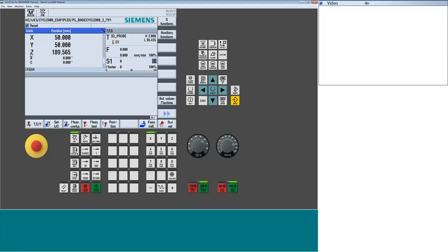So anytime you see a C axis defined, a rotary, because A, B, and C always refer to rotary axes, or should as far as the industry standard. So whenever I see a C, I would expect that's revolving around the Z axis. And then B, if the machine's equipped with it, would revolve around the Y.